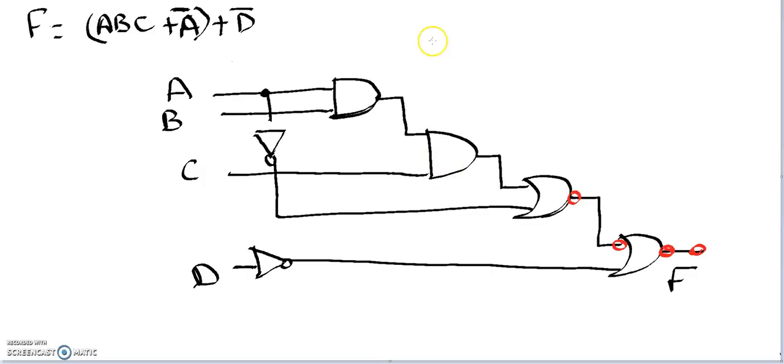We have De Morgan's law that states A or B, the whole bar, equals A bar, B bar. So we want this form, the A NOR B. In order to have this form, the A and the B, the two inputs, need to be negated going into an AND gate. So let's apply this here.